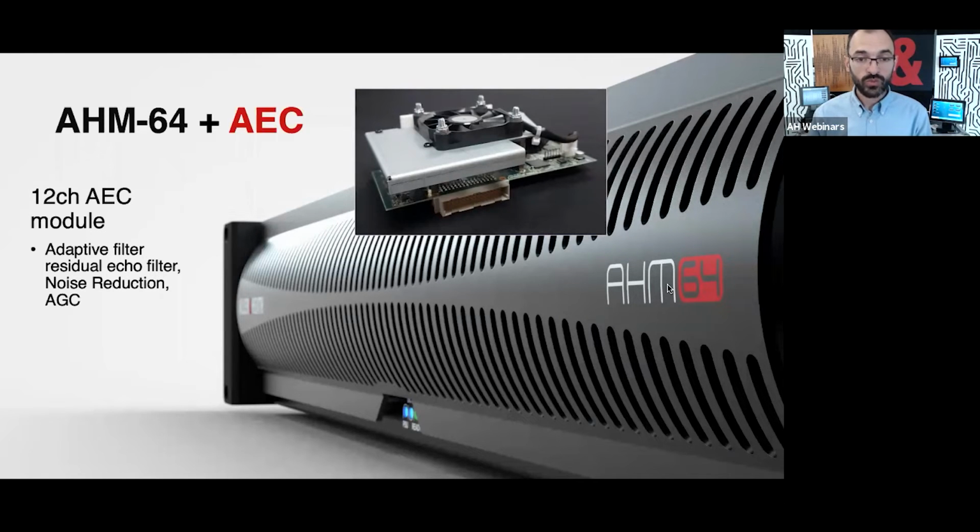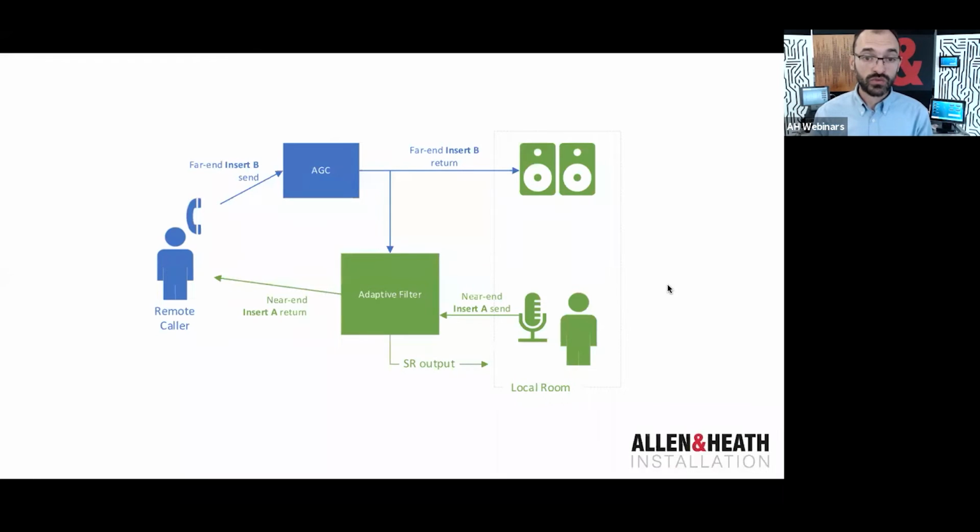So let's have a look at how we would route signals to use with the echo cancelling. And this is just a very simple diagram showing where the echo cancelling would sit in the context of input channels for the AHM64. So it would be assigned using channel inserts. We have 2 insert points for every input channel in the AHM64. One is basically pre-processing, one is post-processing. So one insert in the case of the echo cancelling, one insert sits in the far end input channel, and the other insert point would sit in the near end input channel.